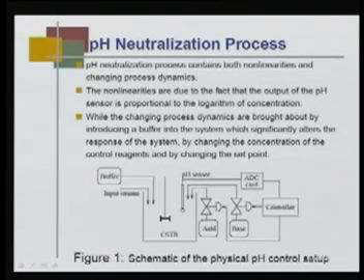pH neutralization process. The pH neutralization process contains both nonlinearities and changing process dynamics. What are these things? The nonlinearities are due to the fact that the output of the pH sensor is proportional to the logarithm of concentration.